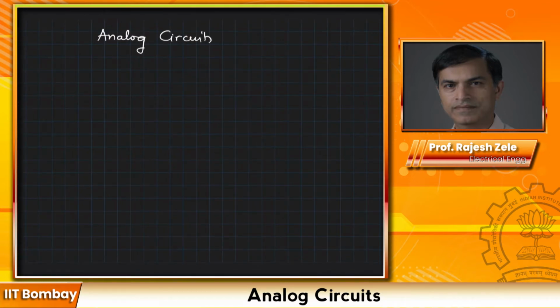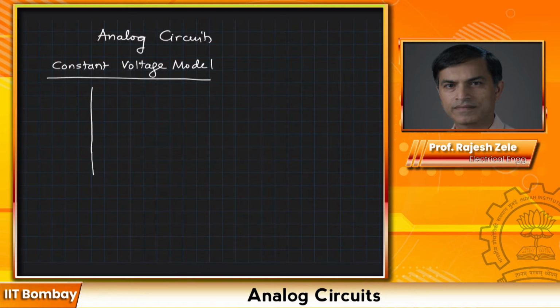Now that we have learned how the PN junction diode works and what the IV characteristics of the PN junction are, we cannot use that equation to solve circuits every time. So we will simplify the device equations into models, and then use the models to analyze circuits. The very first model we are going to talk about is called the constant voltage model for the diode. In this model, what we are assuming is the following. This is the voltage across the diode, VD, and this is the current flowing through the diode.